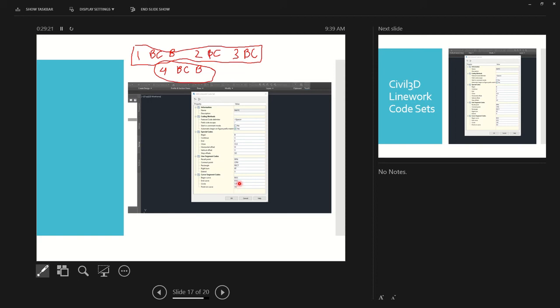Now there's this circle command that you can use, where you would stand in the middle of an object and type in circle afterward, and then you would give it a diameter. So you'd put a space and then 5 for a 5-foot diameter. And it would draw a circle around that point in the center. Not used very often. There's not very many times where a perfect circle is defined out in the field. So typically you're going to want to just use your curve code commands.